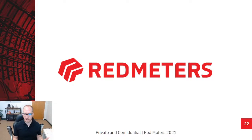The warning signal itself is actually also available as a 4-to-20 output. So if you're not really using the HMI that much and you're mostly using just the raw output, the amperage that's coming out of the red meter, it'll appear as that as well. There are 2 concurrent 4-to-20 outputs. You can set them in our software to anything that you want.